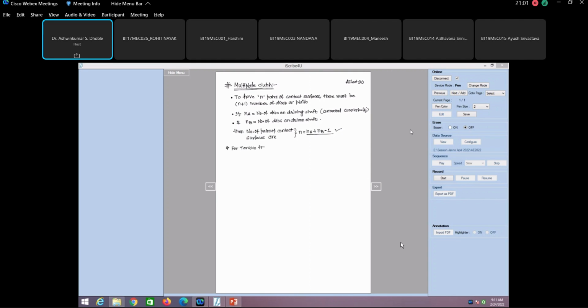Okay, so now the torque transmitted. The expression for torque transmission using uniform wear theory, we can just write down the expression. T is equal to n, coefficient of friction, W, and this expression is the same as previous, R1 plus R2 divided by 2, bracket complete.